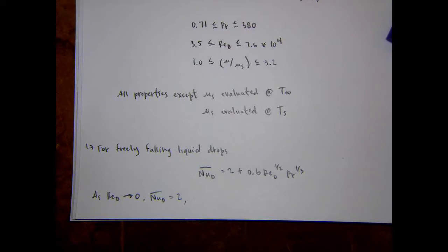So it's interesting that this expression for convection heat transfer, if you say the Reynolds number goes to 0, which corresponds to a 0 velocity, then the Nusselt number expression reduces to this expression for heat transfer purely by conduction to a stationary medium.